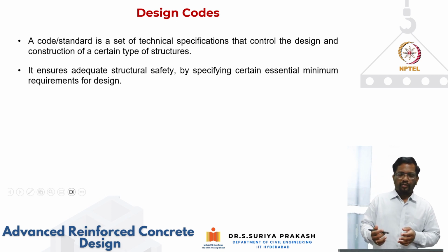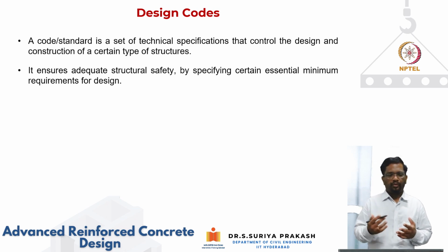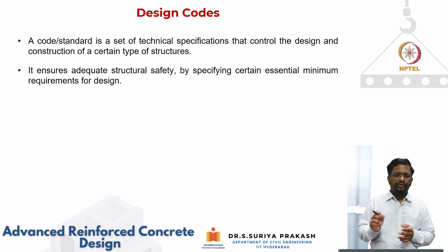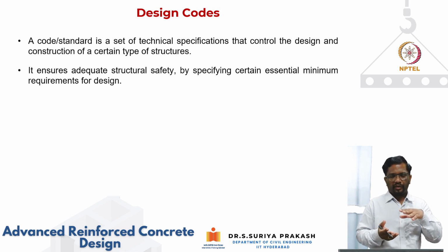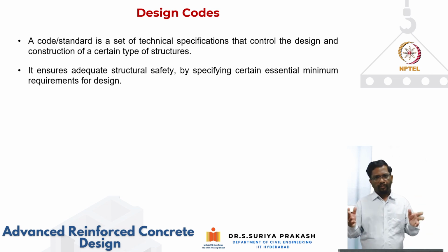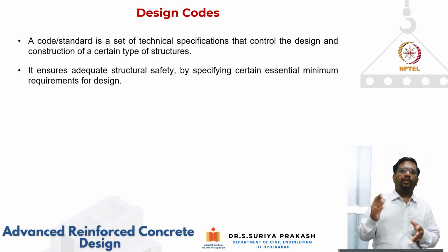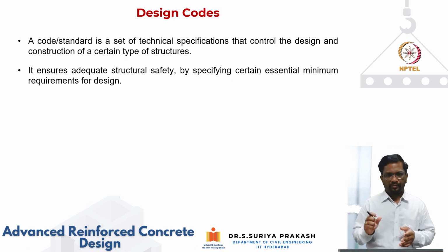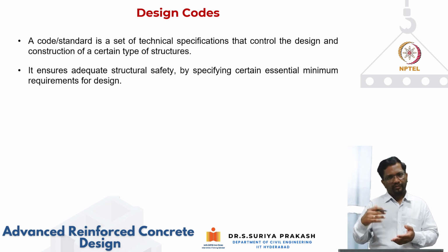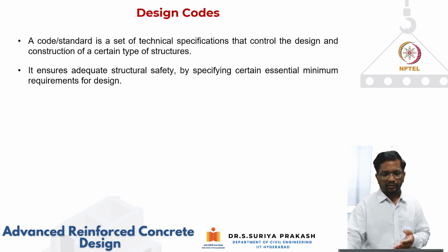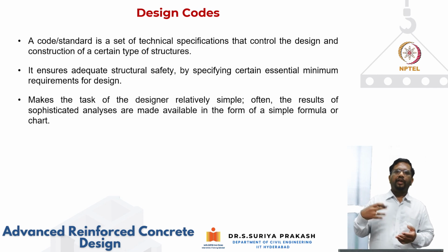So what is the need for the code? Basically, if you follow the code provisions in your design, it is going to ensure adequate structural safety by specifying certain minimum requirements for design. For example, you must have seen the span to depth ratio: depending upon whether we are doing a beam or a slab, and depending upon the boundary conditions, it will tell you what minimum span to depth ratio we should follow. And also, it will give you minimum deflection requirements, that the deflection should be within this specified limit. So such kinds of provisions will be readily available.